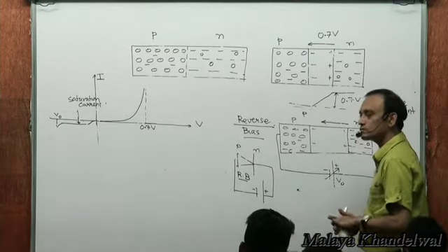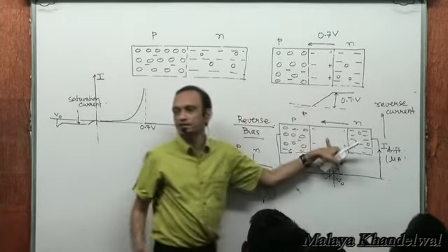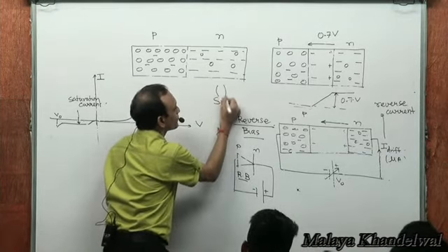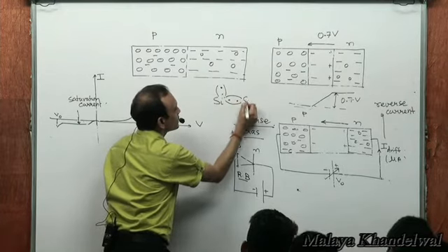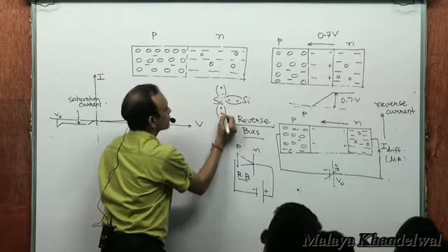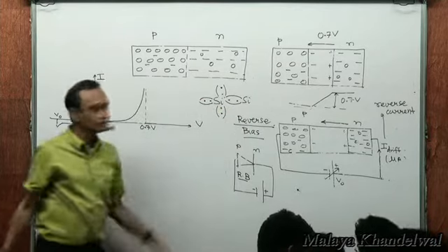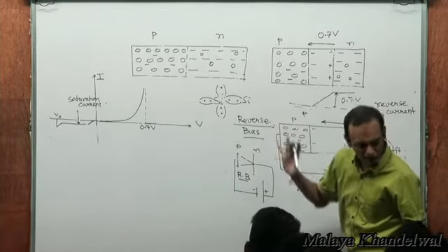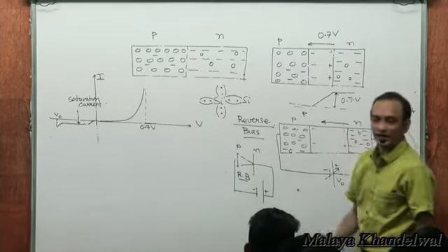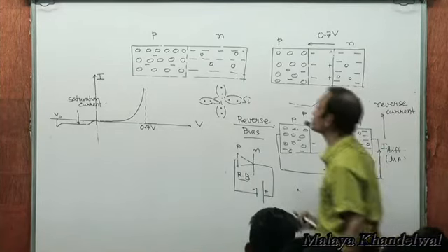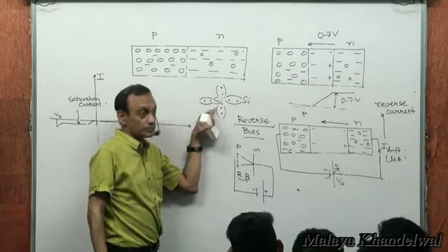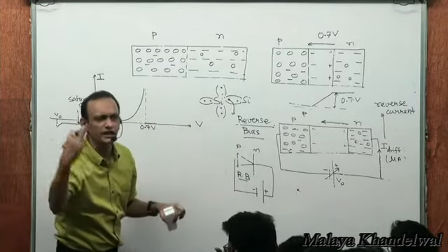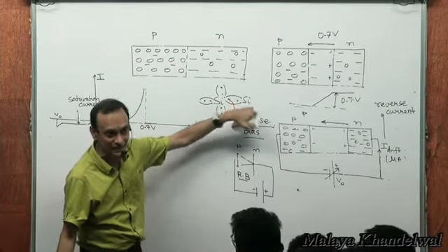What happens is, what I have not shown you here are these silicon atoms. There are silicon atoms here. The silicon atom that you see is covalently bonded with nearby silicon atoms. There are very fast moving electrons here because of the increased electric field, right? These fast moving electrons, what they do to the crystal is, let's say, look at this silicon arrangement. A fast moving electron can hit this electron. It will knock this electron off place because of its kinetic energy. It will knock off an electron from its covalent arrangement with another silicon atom, for example.